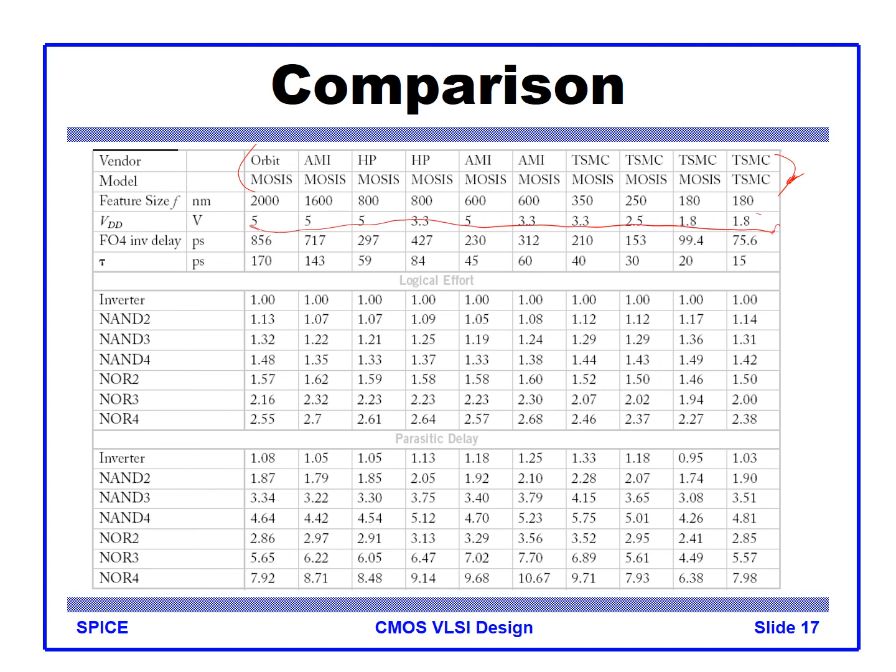The fan-out-of-4 delay scales down for better processes. Approximately, the 180 nanometer process compared to 350 nanometer gives almost 2x, about 2.5x faster, something like that. So the feature size scales the delay similarly.